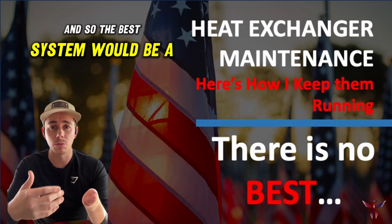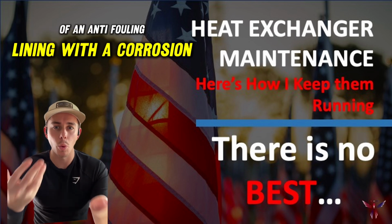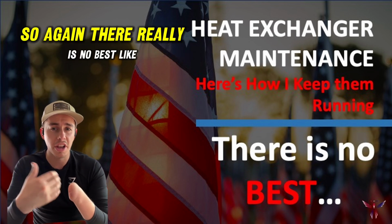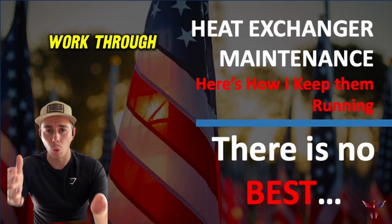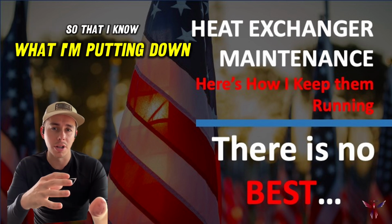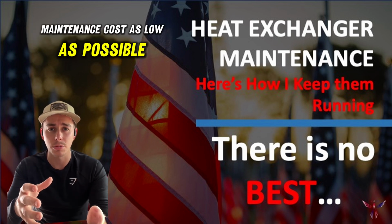And so the best system would be a paste and then have a combination of an anti-fouling lining with a corrosion barrier. So again, there really is no best, like, hey, this is the end-all be-all, but these are the steps I take to work through so that I know what I'm putting down is going to work long-term and keep their maintenance costs as low as possible.